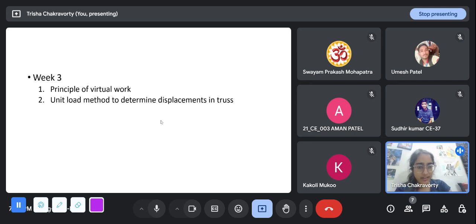So similarly in a truss, this is a beam example I gave. Since a truss element we know can only undergo tension or compressive forces, the displacement will be an elongation or a compression. So that is the displacement at each node, and that will lead to a strain in the member. Stress and strain are two quantities you would have heard from earlier as well. So the stress related responses and the strain related responses are the two we are concerned about.